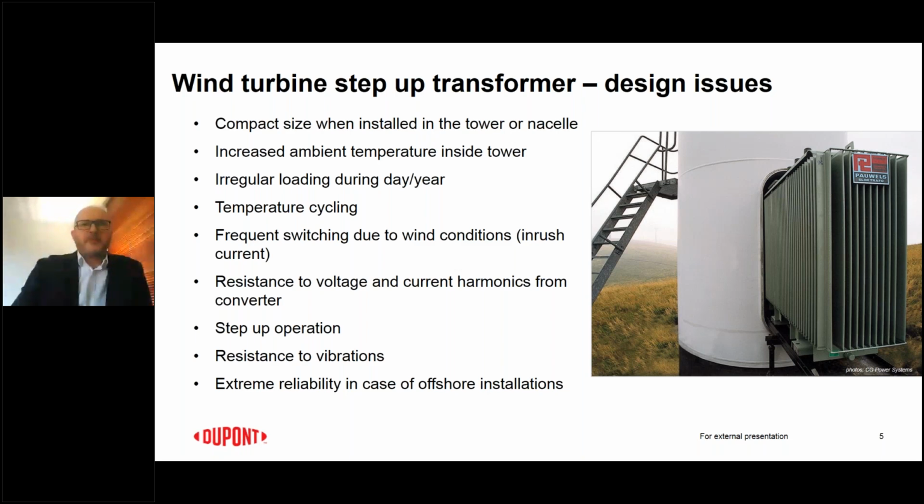They work in the step-up operation, increasing the voltage from around 600 volts up to the medium voltage collector system. Originally, they were basically installed on the side of the turbines. And then with the growth of technology, with the focus on the green aspects, on the footprint, on the visual aspects of the turbines, they started being put inside the turbines.